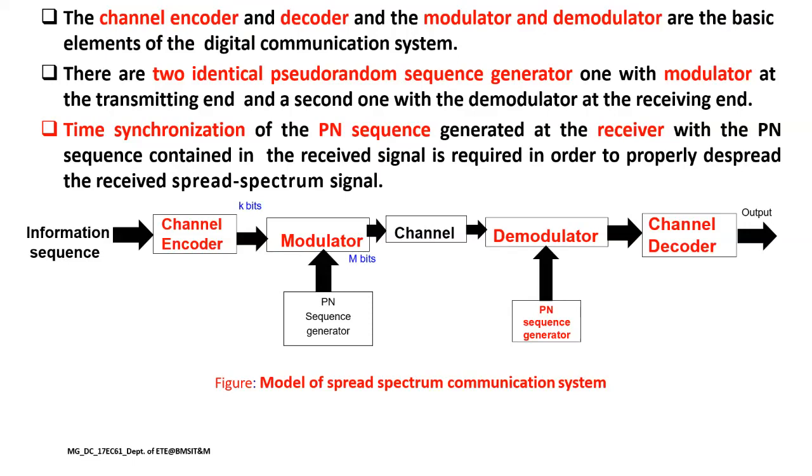Here, the major challenge is the time synchronization of the pseudo noise sequence which is generated at the receiver with the pseudo noise sequence contained in the received signal. This time synchronization is required to properly despread the received spread spectrum signal.